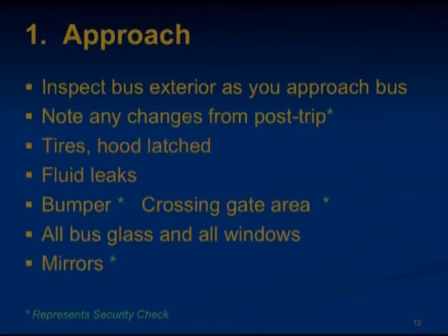We have all been trained on the School Bus Watch program. We must always be aware of our surroundings. The asterisk indicates security awareness check items that may require closer examination during your vehicle's inspection. You will check for any fluid leaks on the ground under the bus. Leaks may come from the engine, transmission, fuel tank, differential, or wheels. Green fluid is antifreeze, pink could be power steering, brown and thick could be an oil leak.